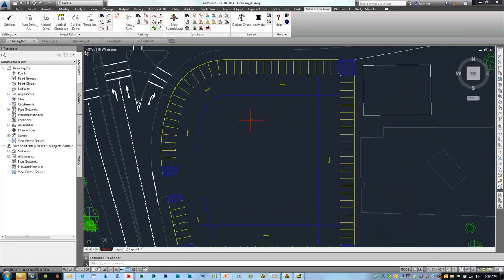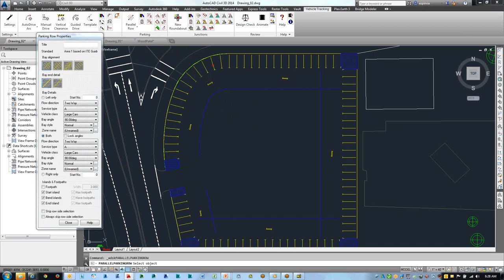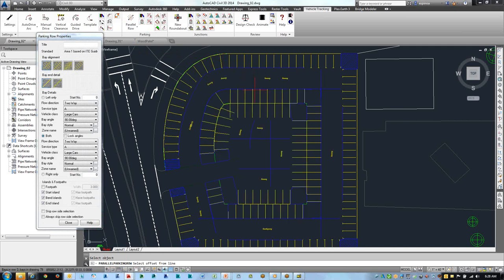Now, the next thing I'm going to do is technically not going to be perfectly accurate, but it'll help us make the decisions that we may need. So maybe someone would then come back and say, maybe I wish to create a parallel row of parking to those that already exist. So as I choose the parallel option, and it asks me which road I am going to be parallel to, I'll pick these outer stalls, and then we can see that I can then place additional stalls here.